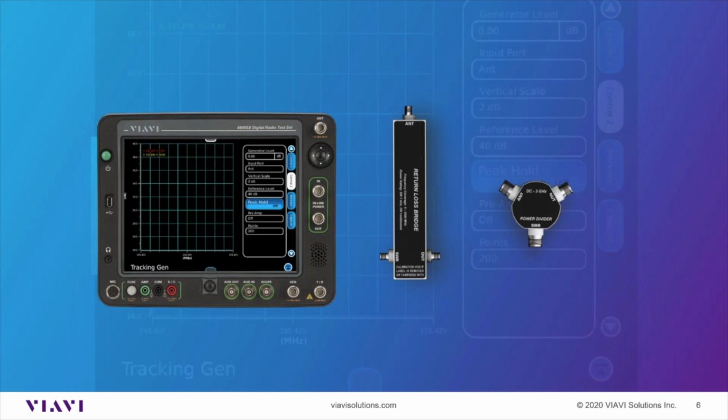Also, Alex asked about using the inline power meter versus the tracking generator to sweep a system. There are benefits to both. The nice thing about the power meter is that it gives you your forward and reflected power already, as well as the calculated VSWR. It allows you to verify that your transmitter is working as well. The downside to using the power meter versus the tracking generator is that it is at a single frequency. So it gives you a very nice snapshot of the performance at that frequency, and that may be all you need. And if that's good, then you're good to go.